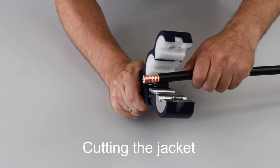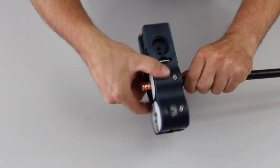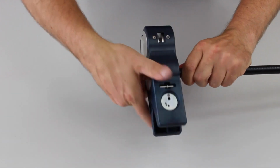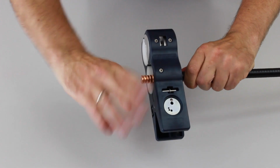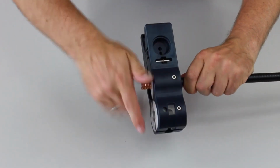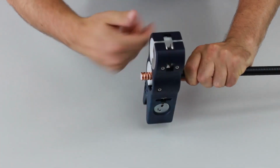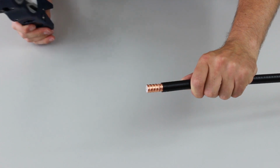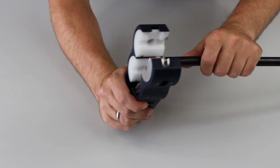Do not apply any pressure. Use the tool's spring force to apply the tool and rotate it all the way around the cable. Only hold the tool at the bottom end. Only turn the tool until you have cut through the outer conductor. If this is the case, use pressure to cut around the cable again 2 to 3 times to achieve the sheath cut that is required for the right connector assembly.